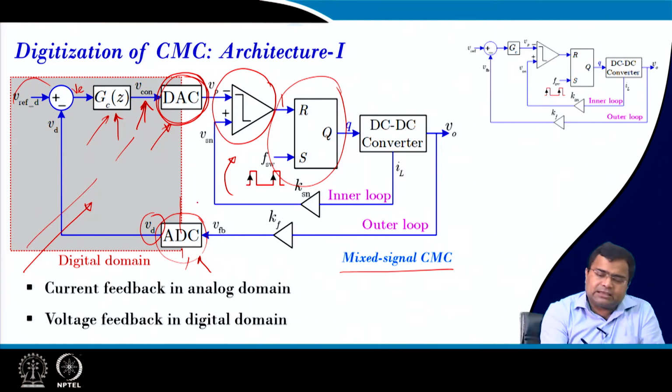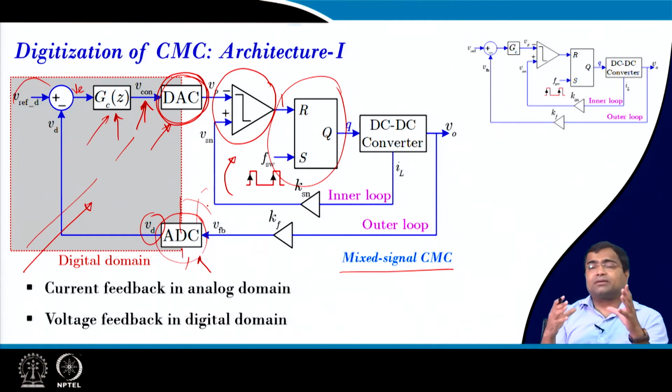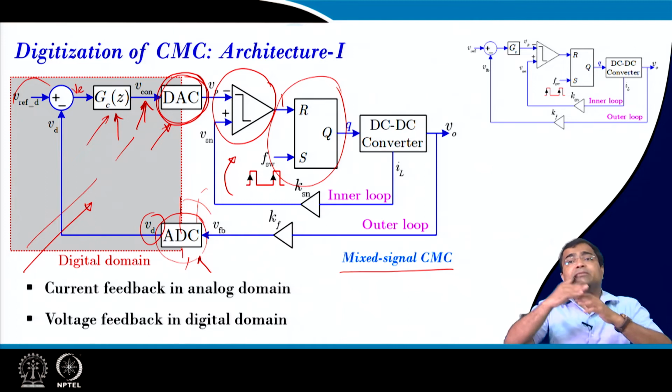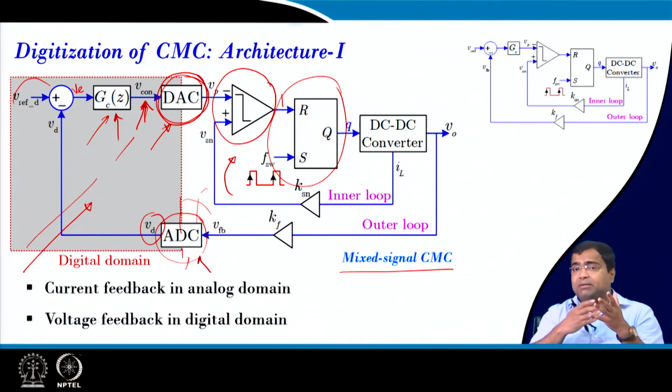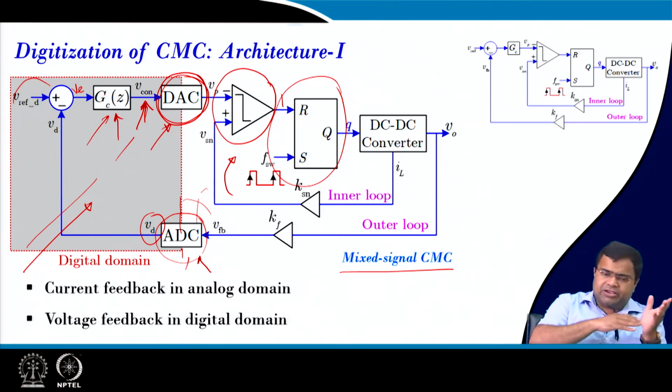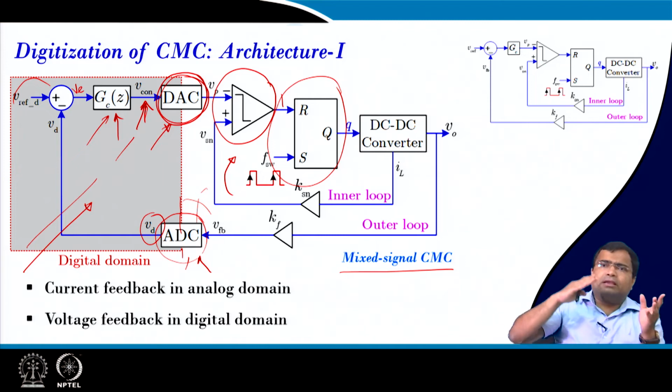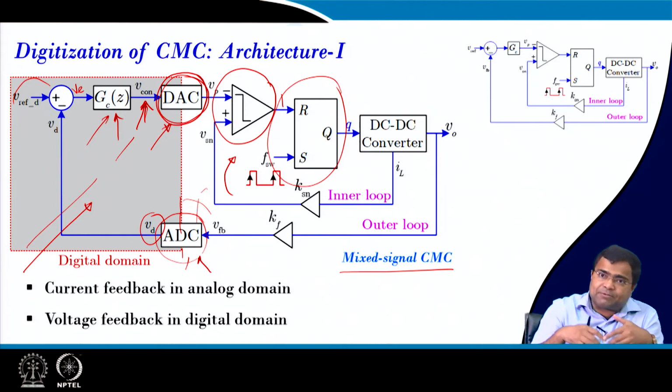But imagine if we take, let us say for example, an analog comparator, and look at how the voltage loop is deviating within some hysteresis band, then you can quickly ramp up this current by means of some nonlinear algorithm. That means you can increase the current very rapidly, and then we can bypass the linear control loop. So all these possibilities are there.